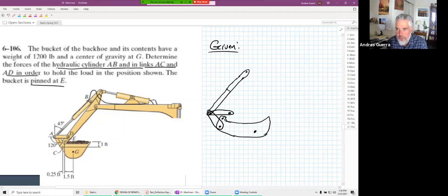We do have some other rigid objects going on up here. This one connects down, wraps around here and comes back. It goes over D and E, doesn't it? So let's make sure this one goes over D and E right there, something like that. But notice that they stop labeling the pins up here, and they stop giving us geometry for this stuff going on up here. And remember, if we don't know the geometry, we can't use it. So there's our general system.